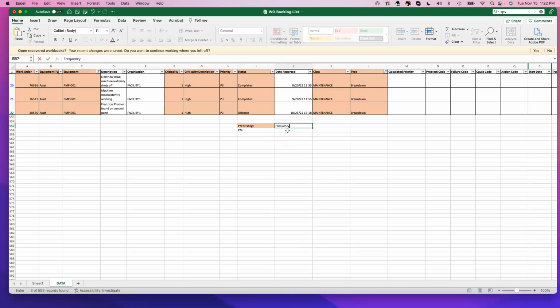If we look closely at those dates reported, we have something happening with that equipment on a monthly basis. So probably if we do a 3-week PM, that can give us some time before to inspect that equipment, make sure that everything's aligned and working correctly.